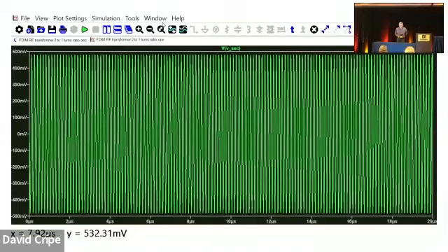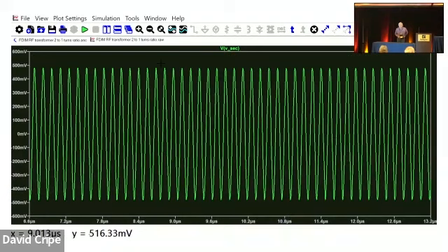I can just move my cursor up there, and it'll show me at the bottom the peak voltage is about 0.485. I said this was a 2-to-1, and it's 1 volt on the primary, so I shrug and say, well, that's close enough, but later I'm going to ask why I didn't get 0.5 volts and see if we can do anything with that.